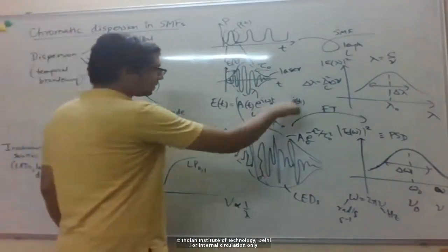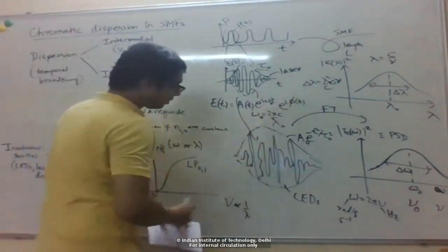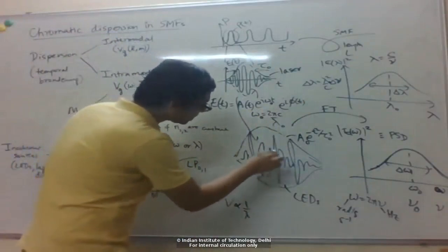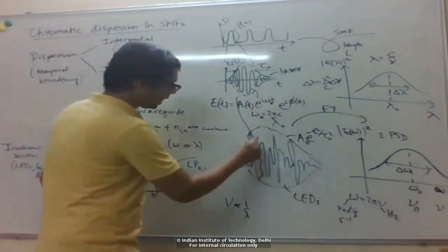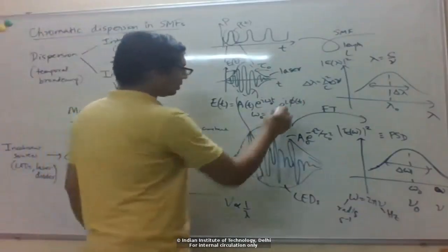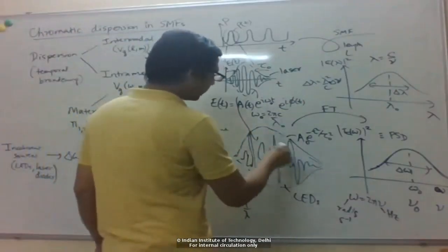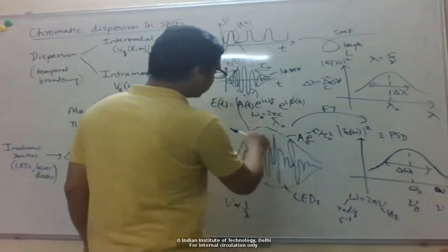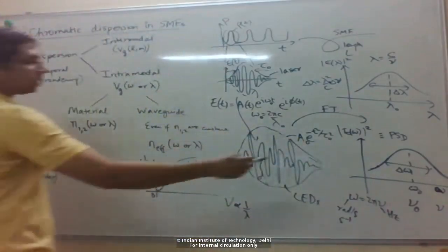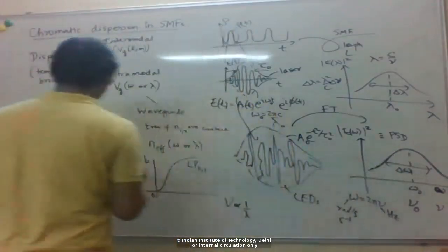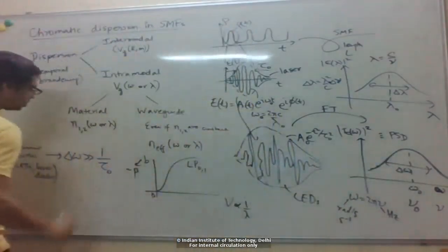But here we're looking at some complex signal, right? So actually, what we're looking at is this, not the envelope. So because of these random phase jumps here, you can see that it has actually a lot more frequency content than just the envelope, right? So that's where the spectrum comes out to be much bigger than 1 over the pulse width.